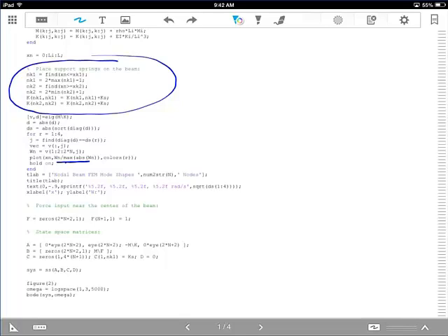And you'll notice here I did put the M inverse, which is supposed to be there, so it wasn't there in that previous example. Now in this case, we're actually trying to put a force near the center of the beam. Here's your input force. And you have to be careful because remember with this formulation that the odd elements of Q are displacement and the even ones are rotation.